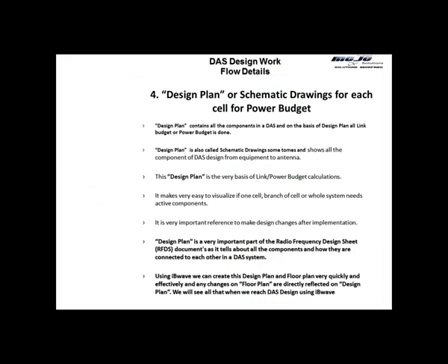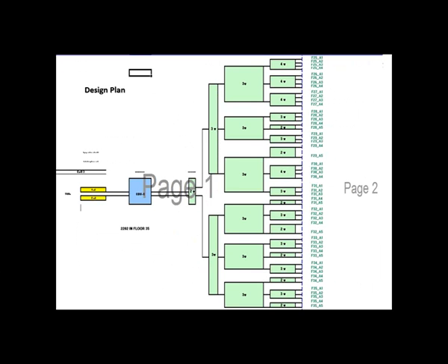Okay, so this is how our design plan looks. If you see, these are the splitters, 3-way, 4-way. This is a passive system, because there is no active component. For simplification, this is our Node B. This is our first cell. This is our second cell. It's going into this combining and duplexing unit to combine them. It's a two-way. These are combined. So on both the channels, both these cells are there. Both these TRUs are there over here.